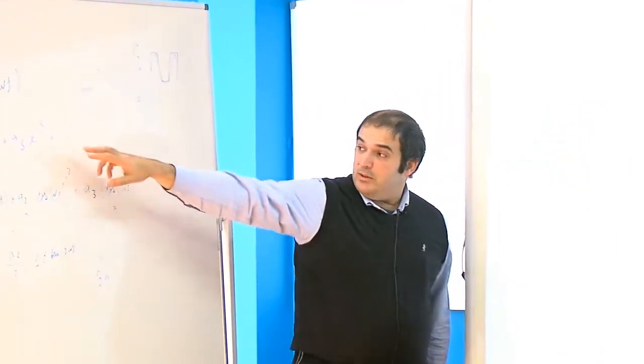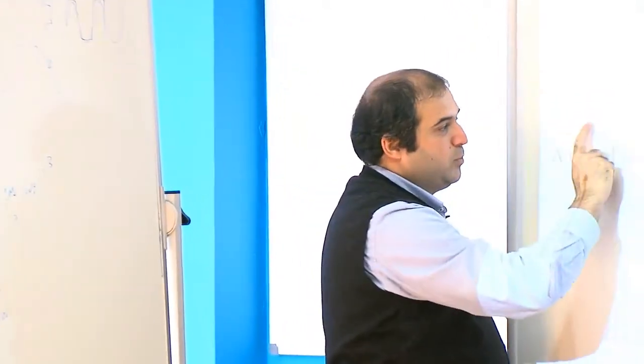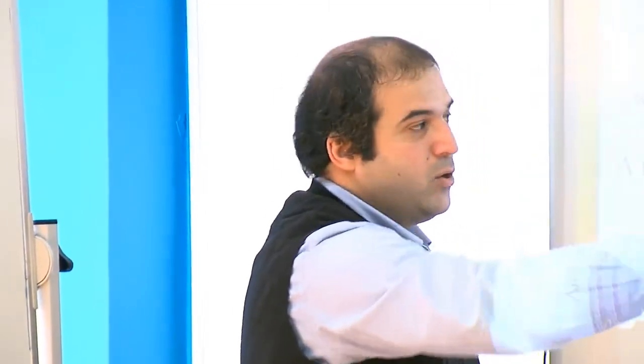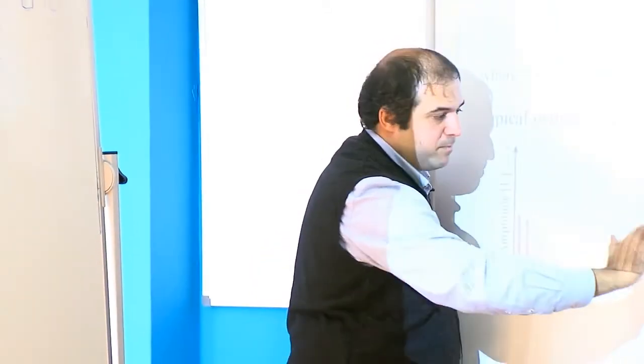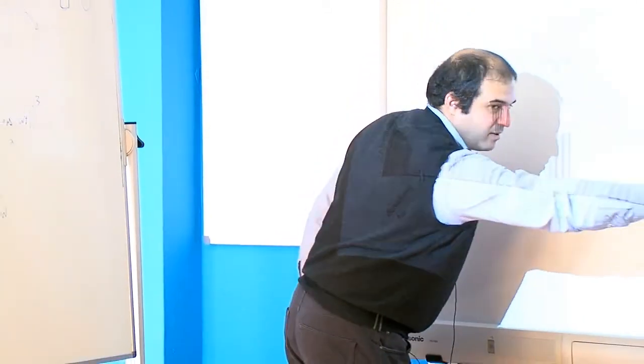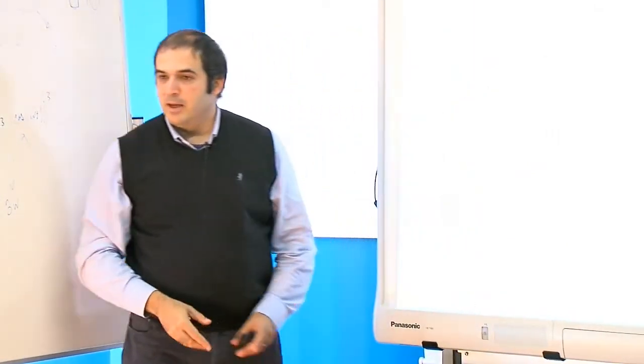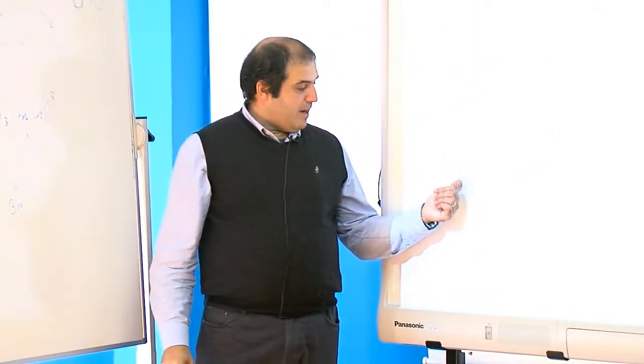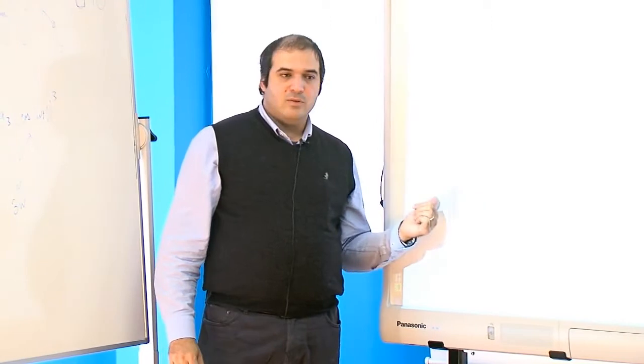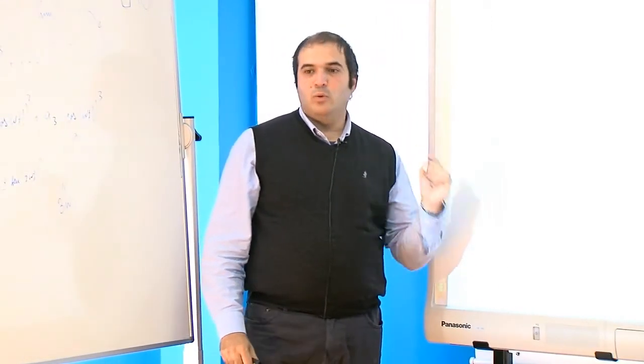Again, if you put it in the polynomial, you'll see the output is going to be like this. So where omega 1, omega k, omega... So you have all the possible combinations you can have of all those tones. So you'll have a baseband that is like this. This is distortion appearing in bands, second harmonic, third harmonic, and so on and so on. Here, you see, I'm exciting a lot of other tones at video bandwidth. I'm no longer exciting only one frequency at video bandwidth.